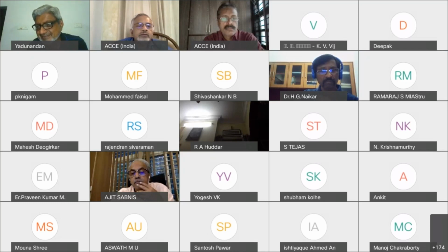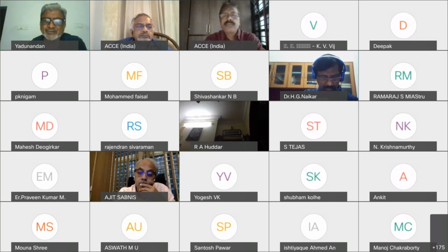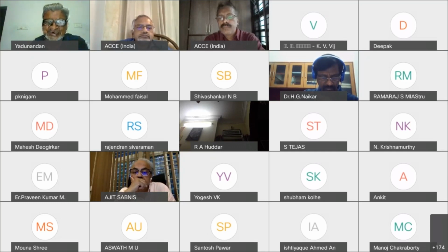Sir, 6 inches. If the span is less, why can't we go for 6 inches? Cumulatively, if we take it, the structure's stiffness... It is not a question of the span, Deepak. It is a question of the height, number one, and the eccentricity that it can cause due to any accidental or unintended change in the tightness of the column. How well are you going to maintain the structure? That is the main thing. That is why we are not allowing that.